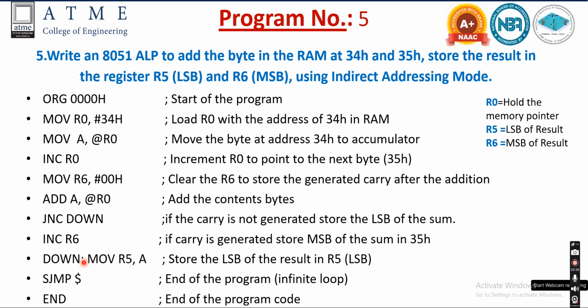In the specified label, what are we going to do? We are going to store the lower byte of the result. If carry is generated, depending upon the data given, you have to increment the MSB of the result. Then at the end, you have to indicate the logical end of the program. This is the brief explanation of the program.